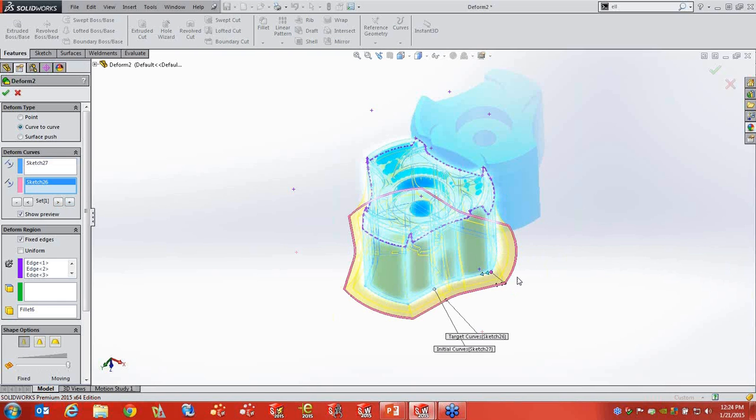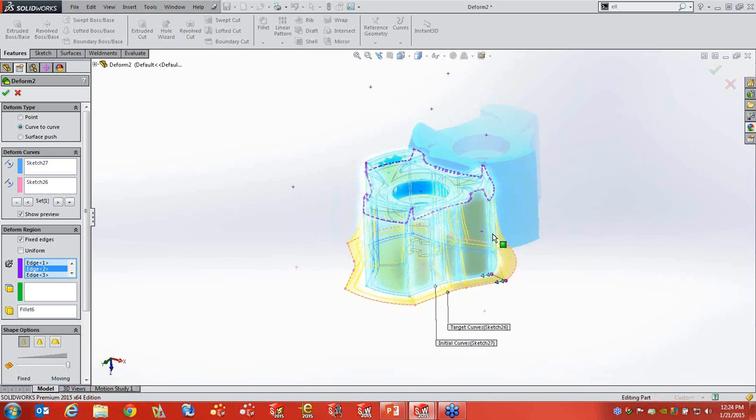I don't want to go back through all the features and figure out how to make that happen. That could take forever. So I used a curve to curve, and then I fixed all the edges where it meets the top features. I said, basically, the only thing it can modify is all the outside edges. The end result, as you'll see as it works through processing, creates 145 new faces on a model that might have 50 or 100 features in a tree.